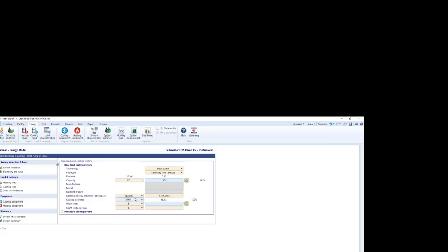basically BTUs per kilowatt of 1.3. In fact, this one should be 4, not 400%. There we go. And the BTUs per kilowatt are 13.6, or the SEER value of that system. So a little bit of a typo there. And then we have the heating system down here. Its conventional efficiency was 70%, but now we're going to a seasonal efficiency of 400%. In this case, a 400% makes sense. That's the same thing as a COP of 4 on the heat pump side of it.